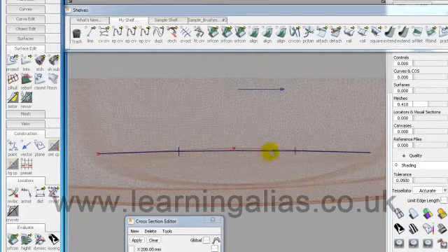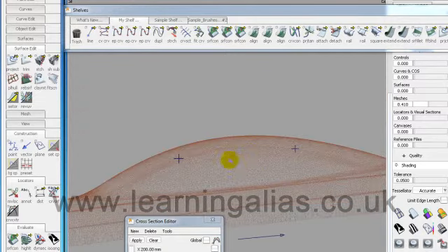So I've got a helper curve, and two construction points, which is just where I feel I would like to join my surfaces. This one, maybe I've gone a bit too far forward because I'm going to be asking the surface to do a lot there, to bend a long way. I could have put it about here, but I'm thinking ahead, and I know that I'm probably going to put a blend in between these two surfaces, the screen and the roof, so that's my reasoning for doing that.